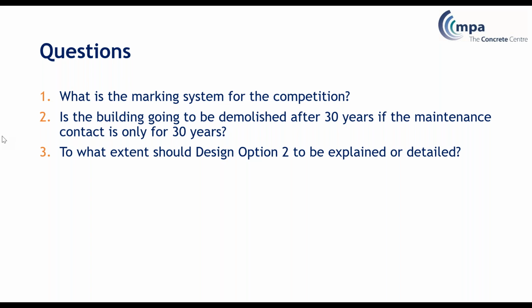We are expecting you to do K equals M over BD squared fck as a design, and design the reinforcement from that sort of thing. We're not expecting subframe analysis and analysis generally.